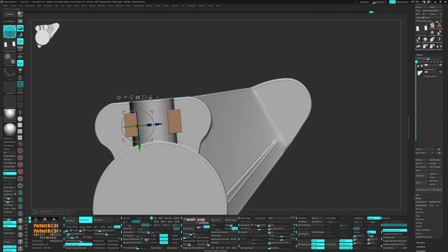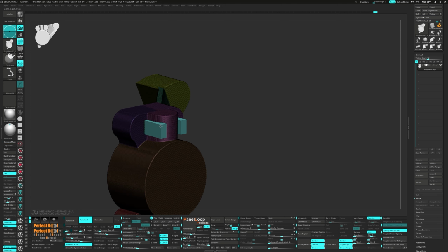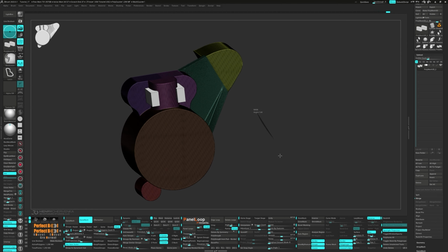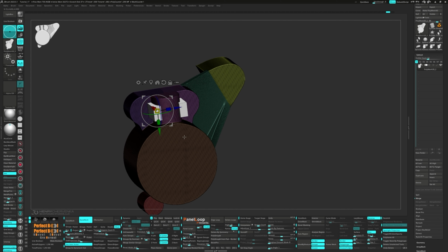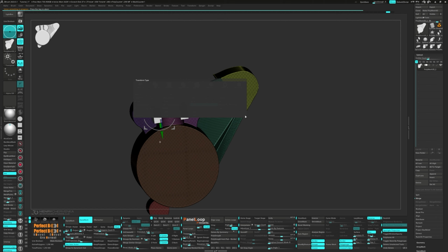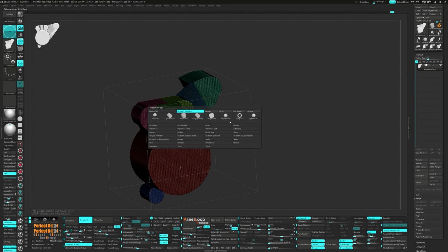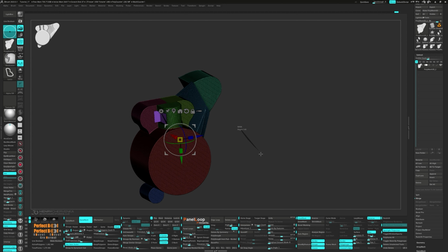Next, merge the subtool down. Let's isolate the cubes and hit Group as Dynamesh Sub. Bring up the gizmo and from the gear, select Remesh by Union. Once that's done, navigate back to the gear and click Accept to lock it in.